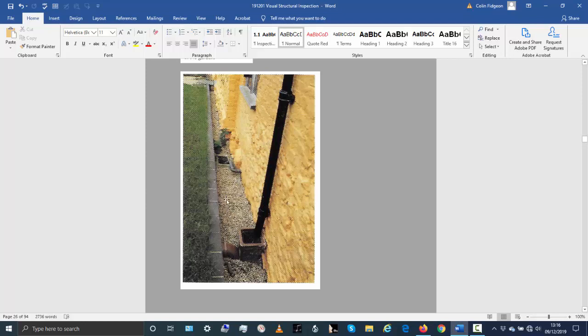So there will be basically a French drain or a pipe in this trench here that will be draining somewhere to a watercourse somewhere, which will take away any water that falls. So any rainwater that falls will go straight down into this downpipe, and it'll get away. Now you might say, well, hang on a minute, surely having rainwater falling down the wall and coming into the ground here will sort of saturate the ground. But it doesn't really work like that.